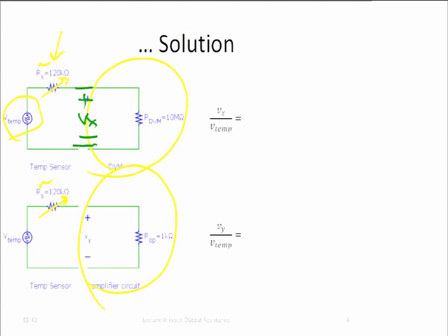So here, what is Vx as a function of the V10? Well, what is that circuit of the resistor RS and the resistor RDVM? It's a voltage divider, right? And so the voltage out, of course, is just given by the ratio of that voltage divider, so that would be RDVM over RDVM plus RS. Now, because RS is much smaller than RDVM, we can more or less ignore this, and then this is very close to 1, right? So if we hook up that voltmeter, then indeed we measure actually V10, okay? And that's what we want. And the reason we do that is because this RDVM is very large. It's much larger than RS, okay?